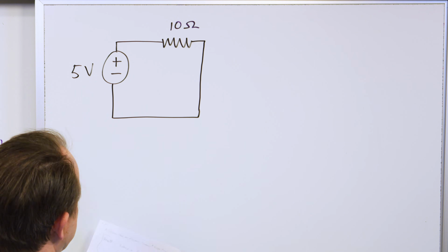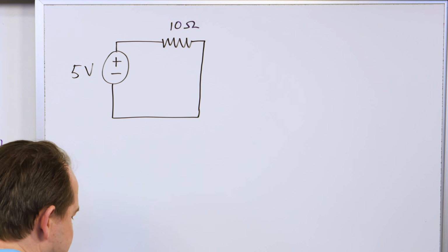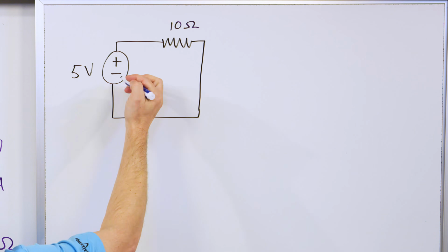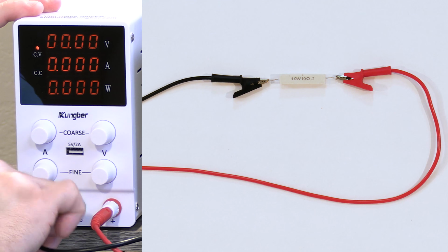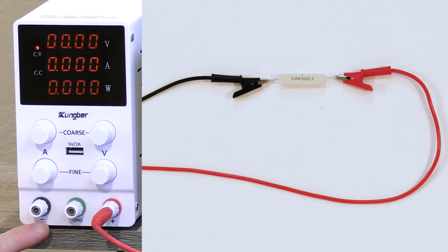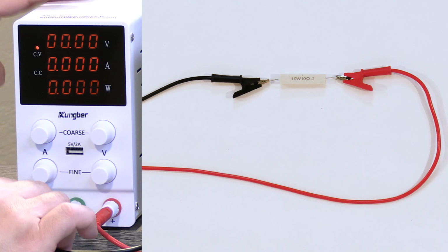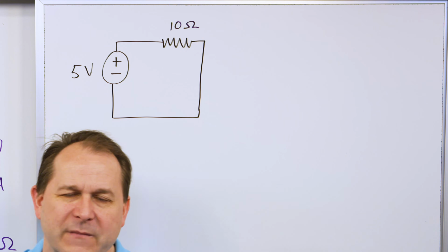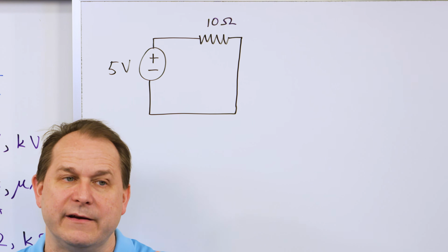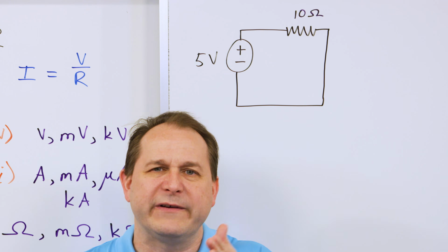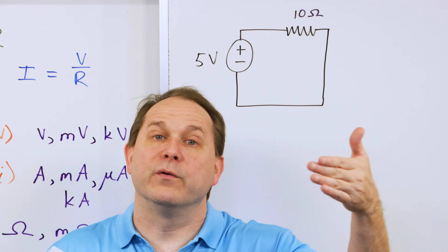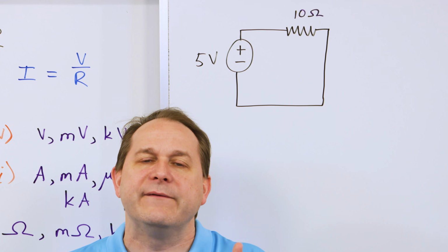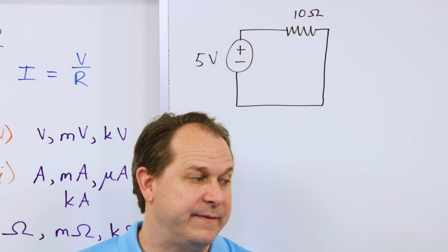All right, so we're going to talk a whole lot more about current in a second, but the way we're going to label our diagram is we know that the actual electrons come out of the negative terminal. If you go over here to this power supply, it's hard to see with everything plugged in here. I guess I can just unplug one of them real quick so you can sort of see. Maybe you can see, there's a minus sign underneath and there's actually a plus sign under the red side here. What that means is that the plus side is telling you the voltage with respect to the other terminal, the minus side. So this means the red wire is 5 volts higher, when I had it dialed to 5 volts, in potential than the black wire.